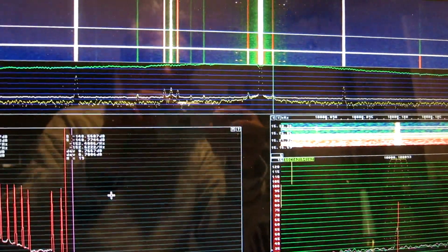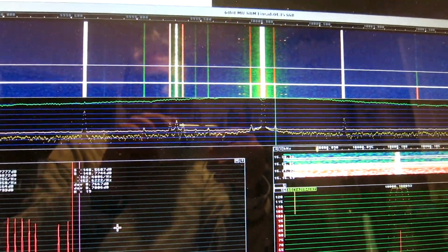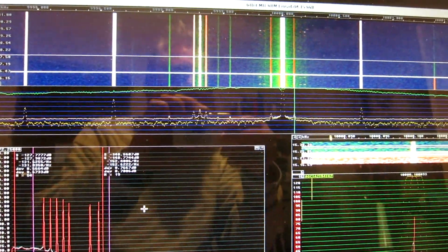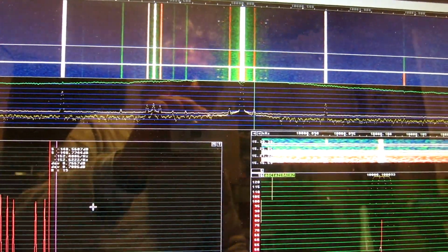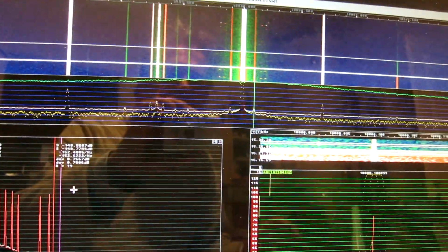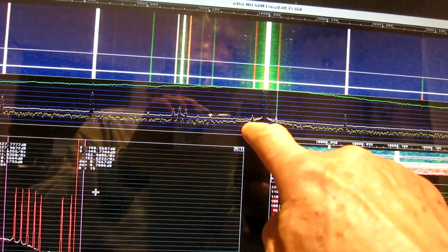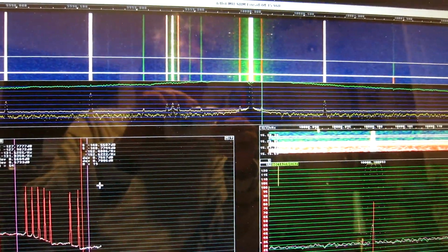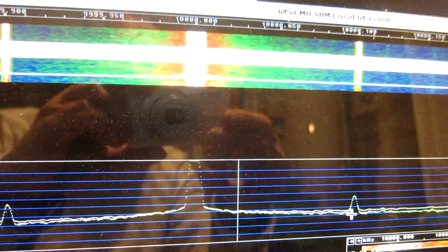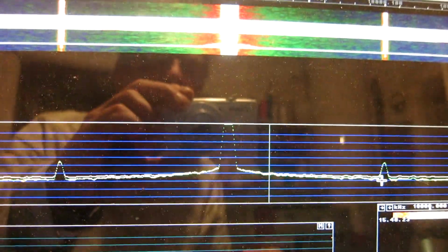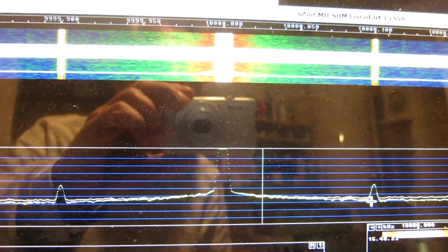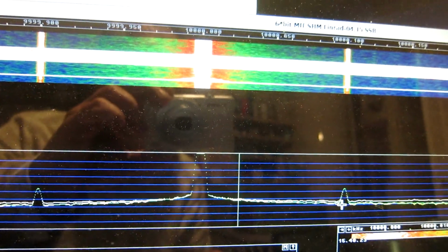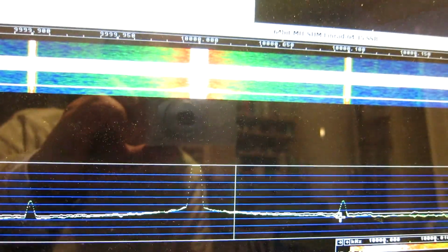It seems, based on this, that I should study crystals with an attenuator setting of 18 dB and just look at a single frequency, maybe something like 25 Hertz, because that's in the flicker noise region here. So I will have to change the setup and do the calibration for that purpose. So these will be the parameters I use to go through several crystals to see how much they differ and to see how meaningful it will be to select them from this kind of measurement.